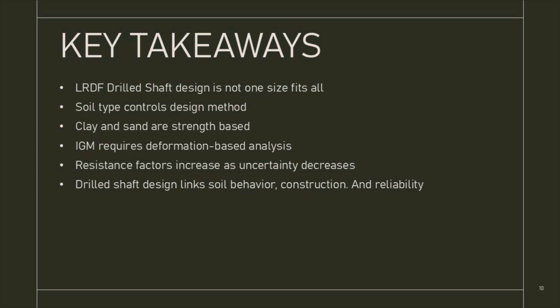These approaches work well, but they can carry uncertainty because they depend on simplified representations of complex soil behavior and construction effects. In contrast, intermediate geomaterials require a deformation-based approach because displacement governs performance rather than ultimate strength alone.